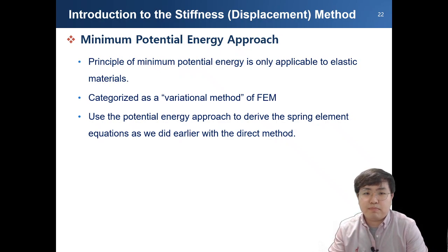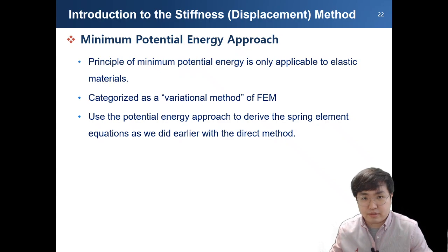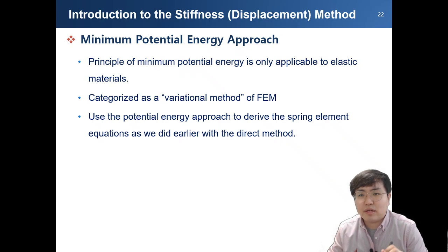Let's think about plastic deformation. Plastic deformation means that the energy will disappear. So a solid structure can store only elastic energy, to match energy conservation, so this minimum potential energy approach can only be used for elastic material.